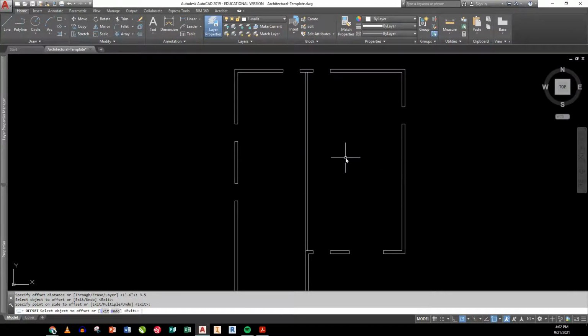Now, in my classroom, we do our interior walls that are just partition walls as 3.5. Now, that's not bearing walls, that's not plumbing walls. The reason they are 3.5 is honestly because that's how big a 2x4 is. Okay, it's a 1.5 by 3.5. And when I build a wall out of a 2x4, my framers are going to build it and they need to know the dimensions. The drywallers are going to come in and cover them. So I don't get too much into other dimensions with that.